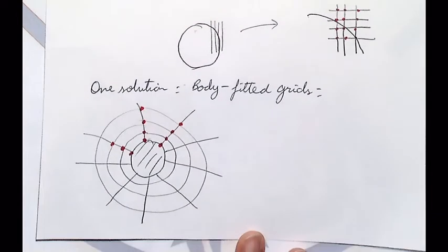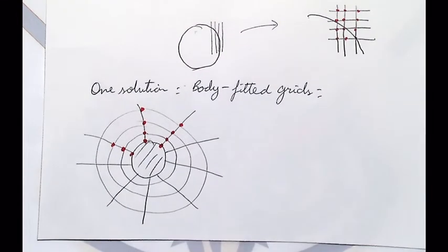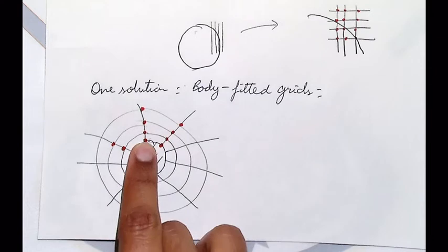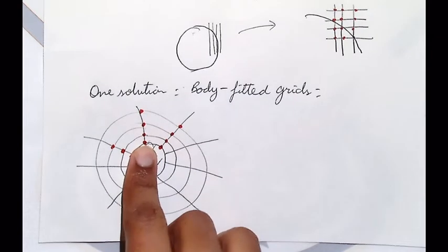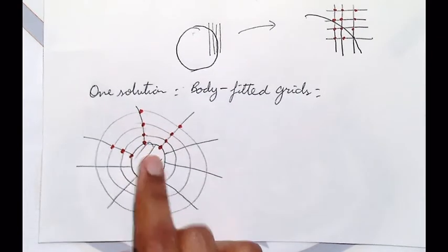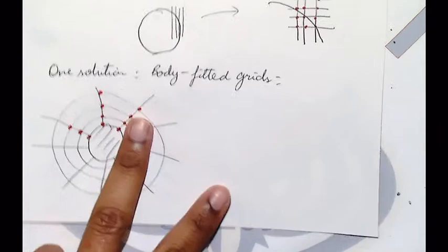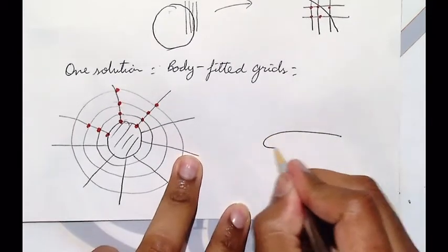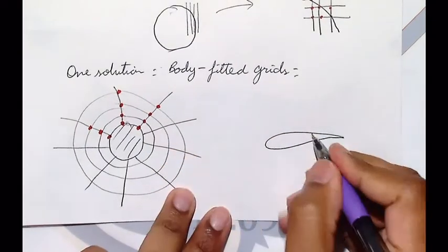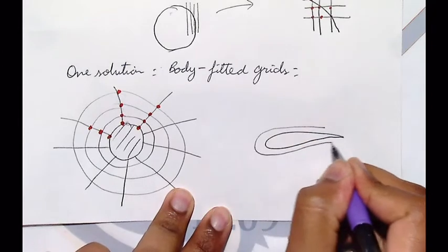In terms of imposing boundary conditions, this is not very different from the flat surface we were looking at before. You would impose u equal v equal 0 here. You would impose dp over dr, where r is the radius, equal to something, similarly as we had derived before, dp by dy equals something. If you have something that looks like an airfoil, you would have another body conforming grid.